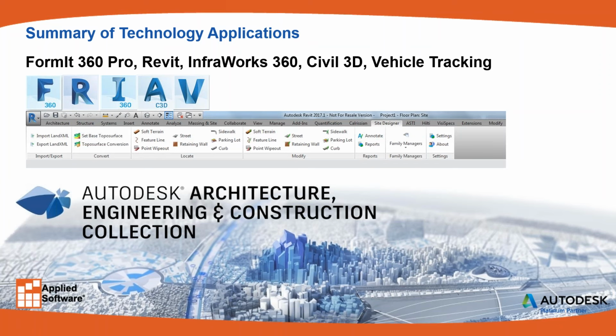And I just want to mention that there is another tool that you may want to take a look at, which is the Site Designer V2 update for Site Designer that can bring in LandXML files into Revit and export LandXML. My experience with it has been a little bit cumbersome. It's not as fluid, as easy to use as the other tools, and so I did not actually show this today in our workflow because I prefer the other workflow, with the extension that shows the integration between Revit and Civil 3D. With that, I'd like to turn it over to Casey for any questions.